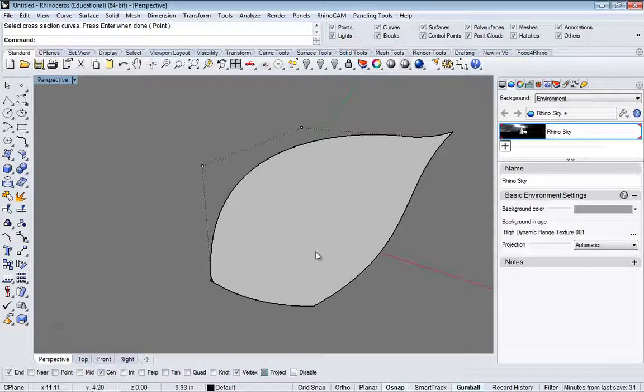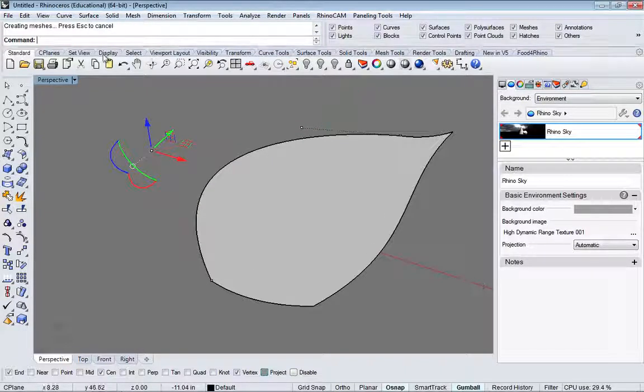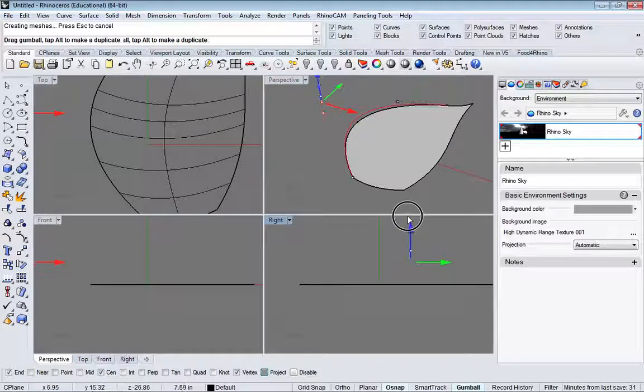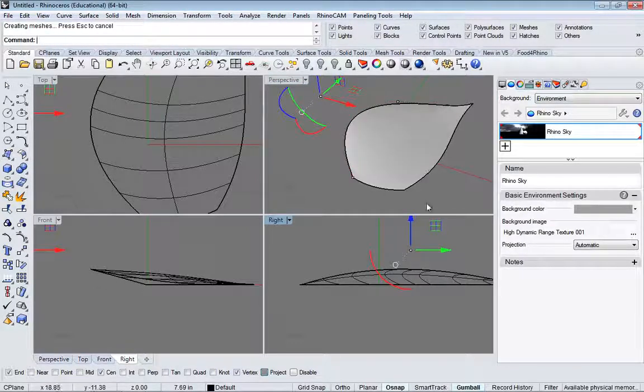Now, because I recorded its history, if I come over here and start to modify this, it changes that surface and it keeps that surface changed. So I'm going to double click up here, go back to the four surfaces. Now if I start to modify this in three dimensions, it modifies totally the underlying structure. So that's what the record history is, and that becomes the basis of how Grasshopper works and being able to make parametric models based on that. So that's a really handy tool to use. Just keep that in mind as you're going.